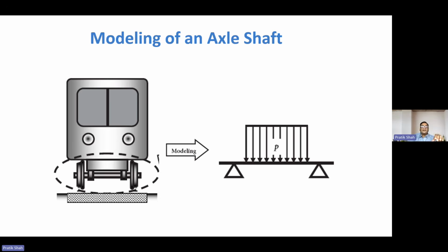So what I would like to stress upon is that interpreting the physical model is very important when you use a software like this. Even if I go into details of this, the load is to be shared between the rear and the front axle. So only half of the automobile load will be coming on the rear axle. So this is how you should depict the physical condition.